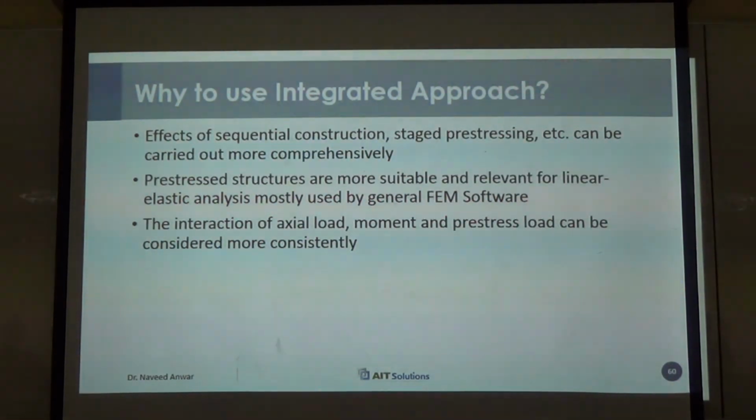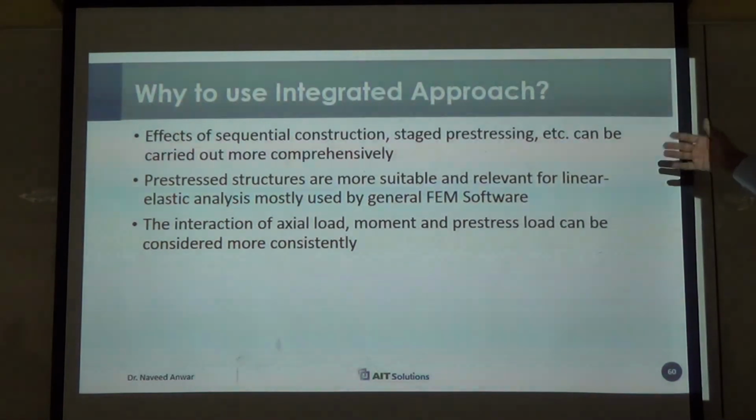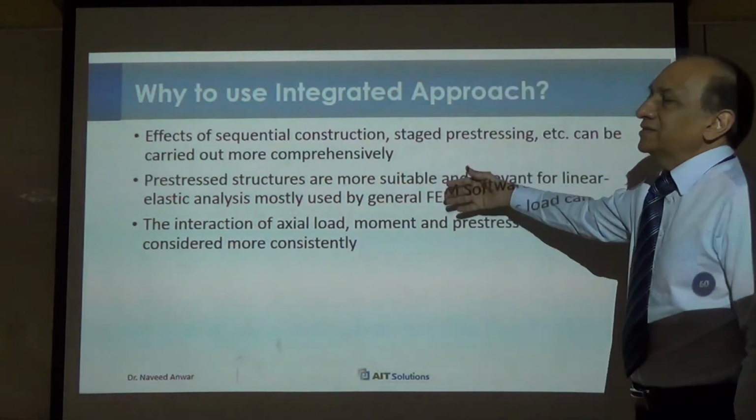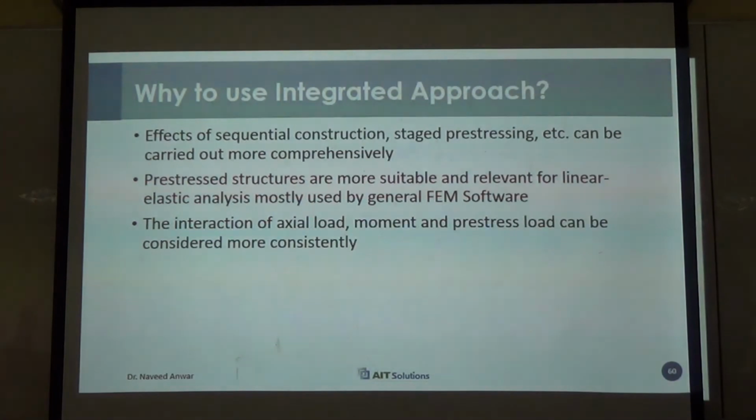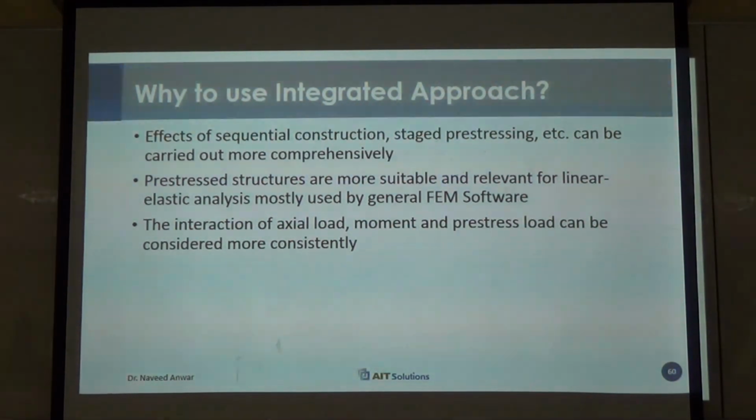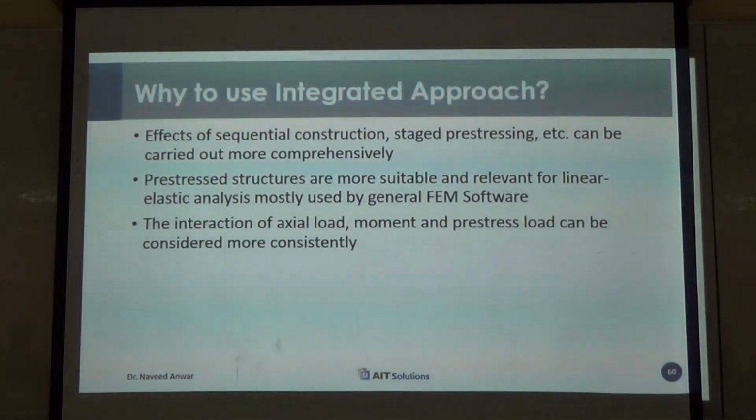So the effects of sequential construction, stage pre-stressing, etc. can be and need to be handled comprehensively by using this concept. So the main task of a good bridge program is to automate this whole process. So you tell the program that you're going to construct this bridge in 20 segments. It will automatically calculate how many pre-stressing cables you need at each stage, and it will include that pre-stressing in the analysis. So it automates a lot of that stuff. Otherwise, it is very complicated.